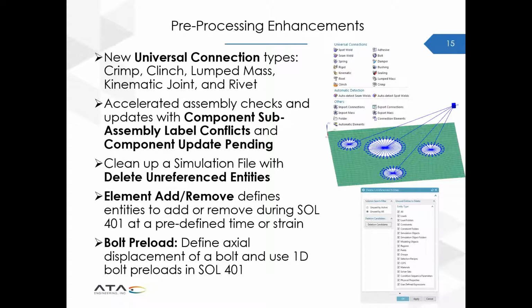I have a few other things that I'm going to point out before we hop back to NX now, starting off with universal connections. Universal connections are valid across multiple solvers and analysis types, and they can be specified on either finite element entities or geometric entities. The benefit that universal connections provide is they let you avoid manually remeshing these components, which really can save significant time if you need to switch solvers or analysis types or anything like that.